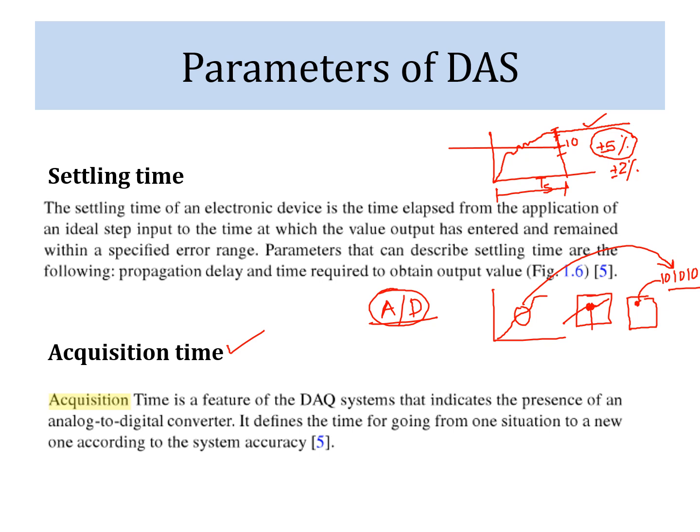Even it may be more than that due to other delays or propagation delays within the IC. However, it may be in milliseconds or even microseconds, but there is some acquisition time which we have to keep in our mind regarding programming and decision making.